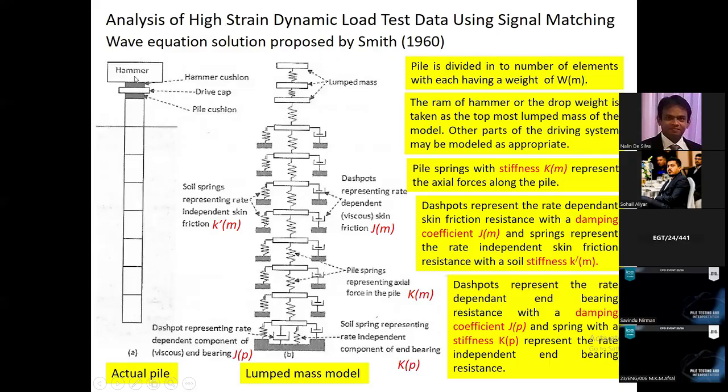given hammer blow, right? You already have a measured response. By using the sensors, the accelerometer and the strain gauge, you have already measured the actual pile force response.